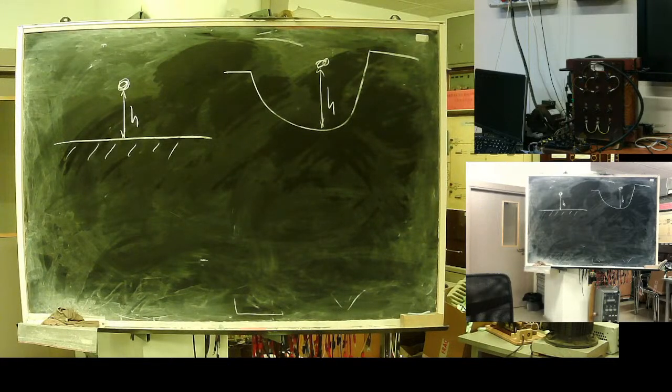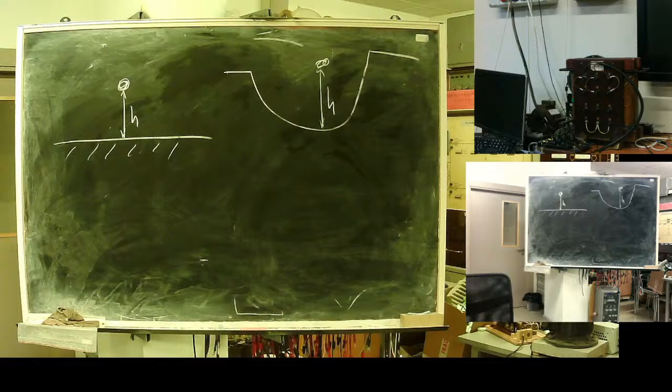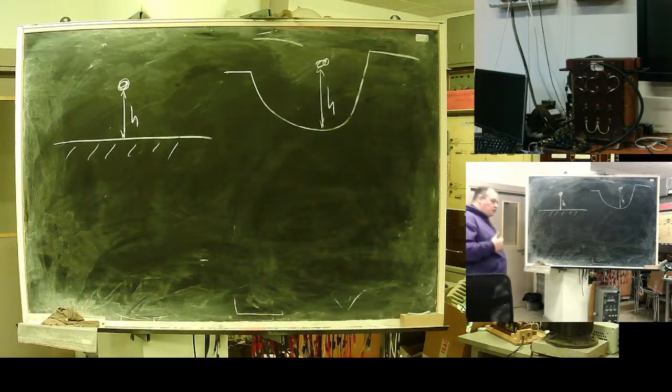In some German-speaking countries, Rüdenberg's model is used to this day, but in my view it is not practical, because Rüdenberg was against modal transformation. Rüdenberg's model is not suitable for symmetrical components. Actually, it can be used, but in general Rüdenberg was against symmetrical components.